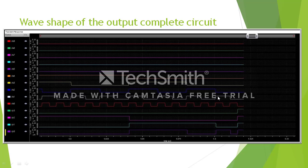And when the input pin A1 is high, whether the A0 is high or low, the output pins Y3, Y2, Y1 and Y0 will be showing 0 0 0 1, which is the active input pin A1. Similarly for A2, this is the A2 wave shape, and when the A2 is high, then the output will be 0 0 1 0, which is the active input of A2.